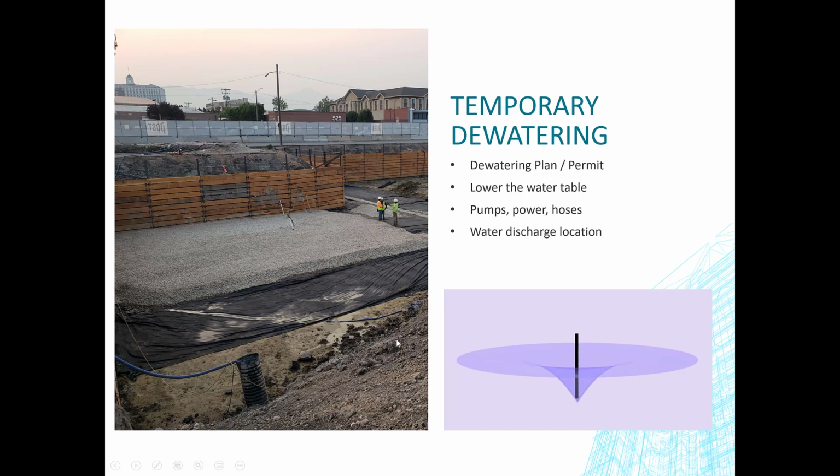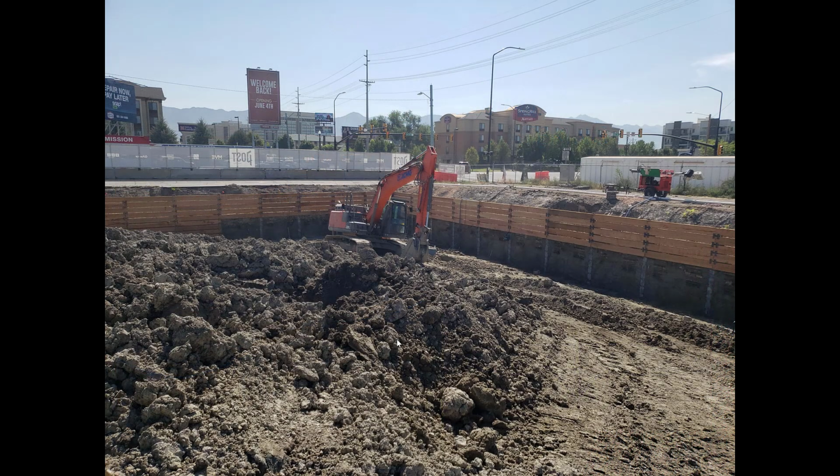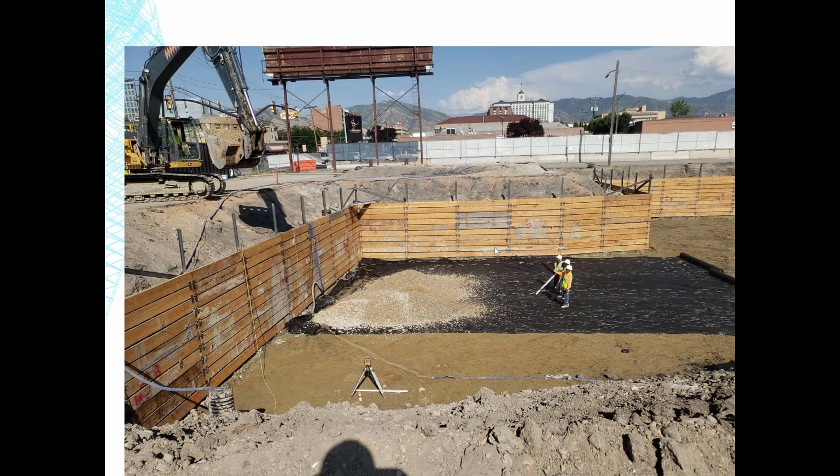Let's move on past the temporary and get into the actual dewatering of a building. As you see the excavations start to go down, you don't see any water right now. On the far side right here, you can see the shoring continue to go down. The piles over here, they haven't added more to it, but they will be. They're starting to go down. They get down to a part, you can see that they've put in their temporary dewatering system.